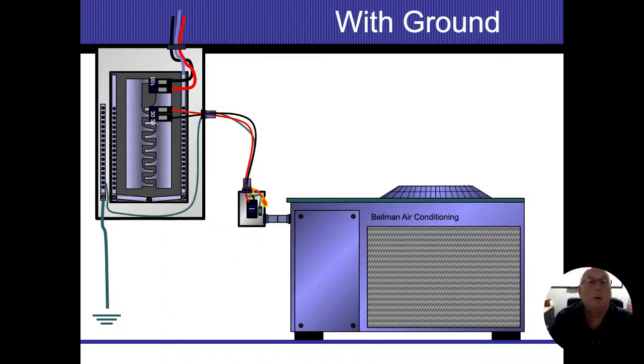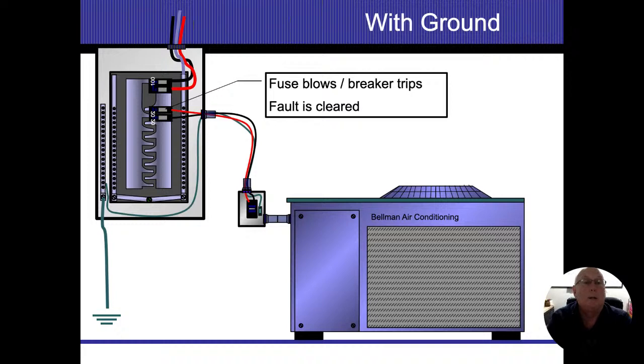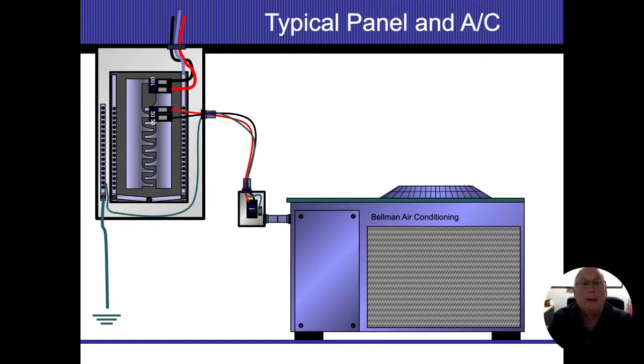So now we took a green wire, we ran a ground to our grounding bus bar. We do have our bond inside there as well. So now that wire comes loose and energizes our case, which is going to energize our ground wire. Because that bond screw is there, it's going to now energize my neutral bus bar. That neutral bus bar allows for no resistance whatsoever. So we're still going to have 5 amps go down the grounding electrode conductor, but we're going to have unlimited amps going up the neutral wire. That unlimited amps is going to be far more than the breakers, so they should be tripping instantly, and then our power's turned off and nobody's going to get hurt. That's our main goal.